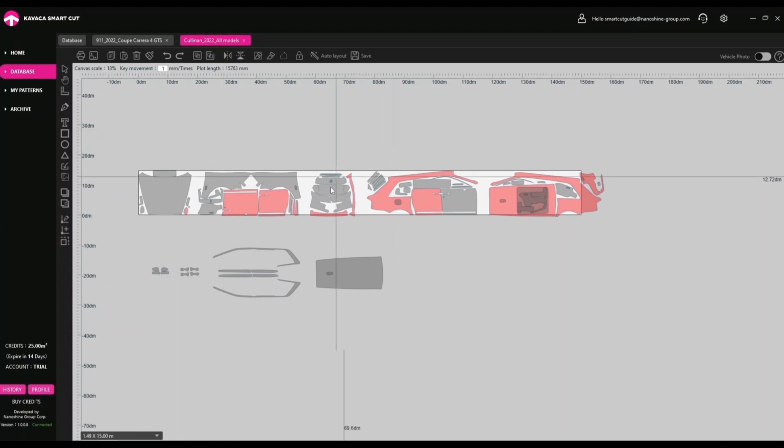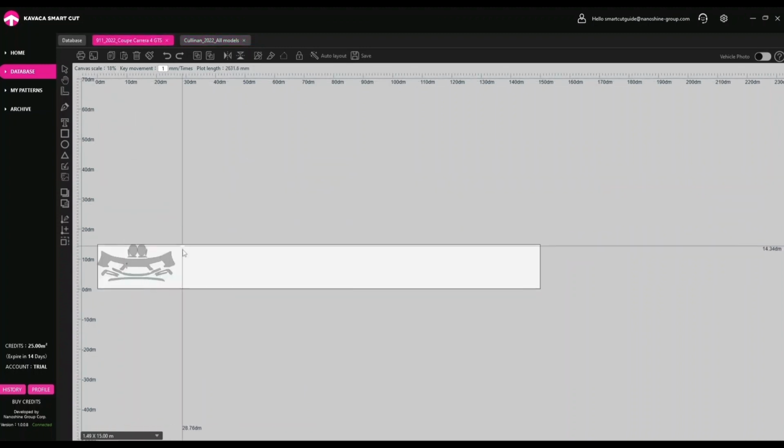Select the desired pattern, copy it by clicking the Copy button on the toolbar, or use the keyboard shortcut Ctrl+C. Then return to the Work tab, paste the copied pattern by clicking on the Paste button on the toolbar, then move the cursor to the place where you want to place the patterns on the canvas and click the left mouse button. Or use the keyboard shortcut Ctrl+V. The pattern will be inserted at the location where the mouse pointer is located.